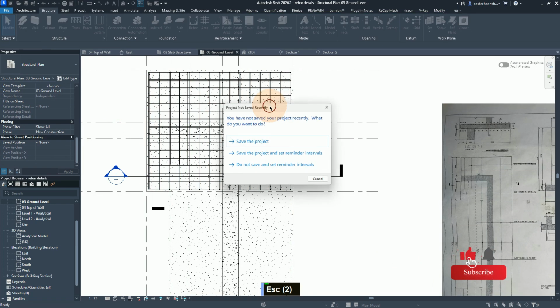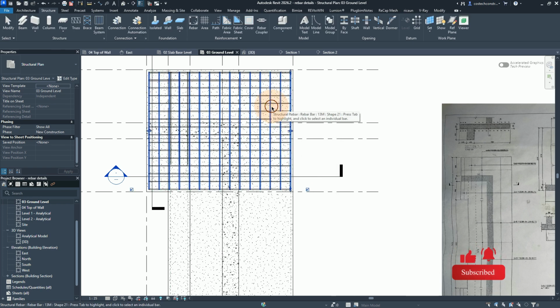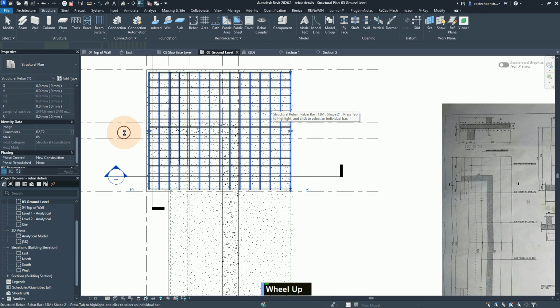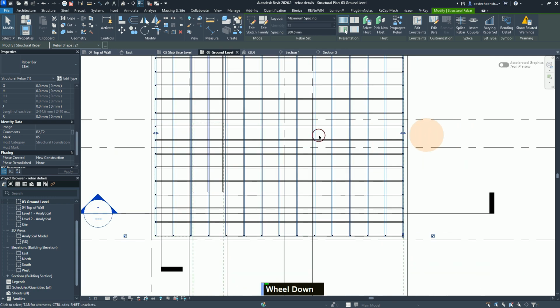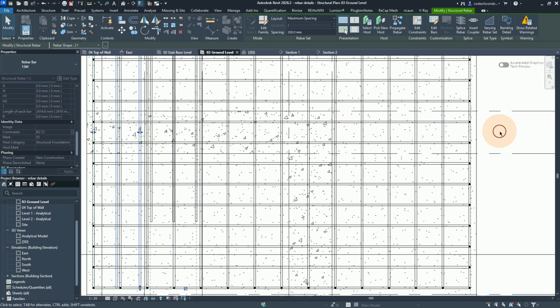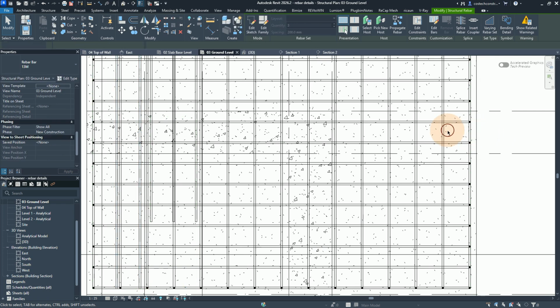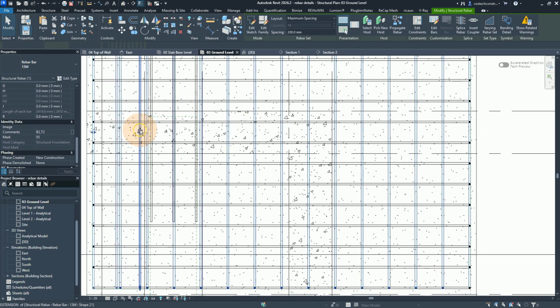Now we can select the Rebar Set. Okay, I'll select any Rebar Set, this one. Then I'll drag its endpoint. Let me drag the endpoint. So we'll select this one, the endpoint here, and we can drag it. Let's first drag it up to somewhere here. I will click outside. Then I'll select the other Rebar Set, and we can drag it up to here.